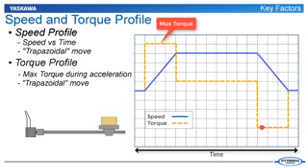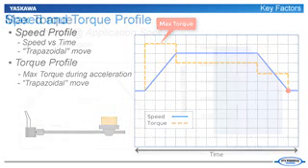The reverse torque during deceleration is not as high as the forward torque during acceleration, since friction also helps decelerate the load. And when friction torque is high, a forward torque may be required during deceleration so that the motor doesn't slow down too quickly.